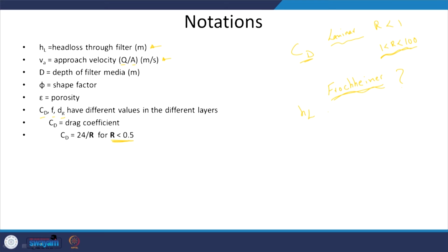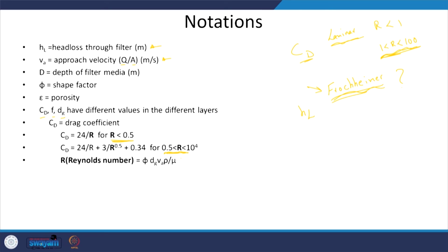Again, we will look at this head loss. If it is laminar flow it will be different, and head loss if the Reynolds number is in this zone will be different. So, that is something to keep in mind. Do not look at me for the reference for this particular spelling, you should check the spelling. When the Reynolds number is relatively low, versus in the transition or particularly the turbulent zone, we rarely get turbulent flow conditions. You can calculate Reynolds number obviously, and in this course I will give the relevant equations in a sheet, but depending upon which exams you want to pass, they might need you to memorize relevant stuff.